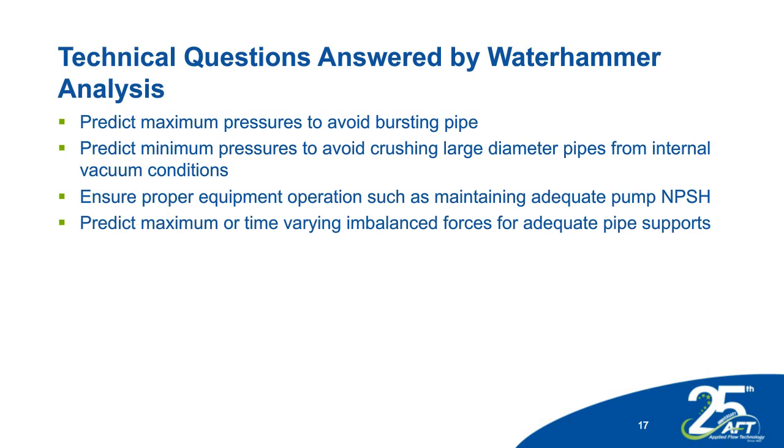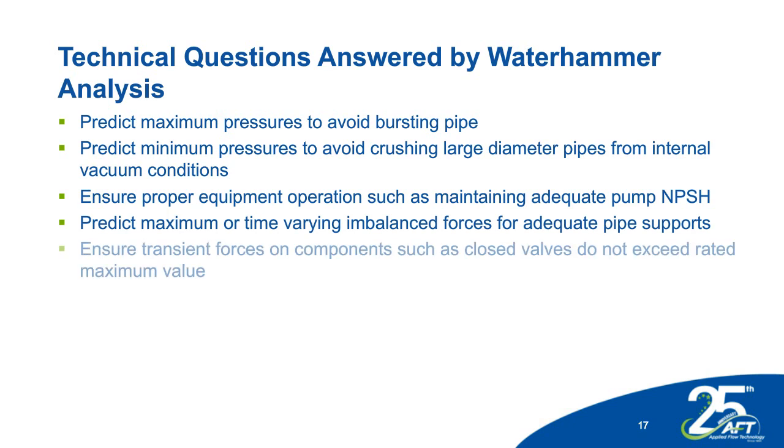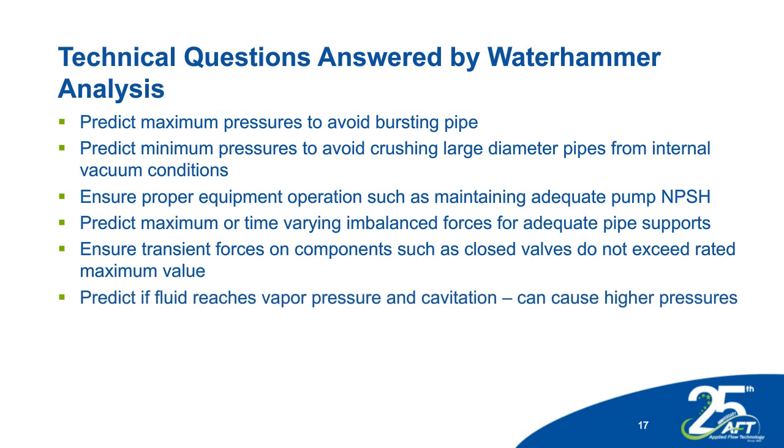It can help you predict transient forces. So when your pressures are changing throughout your system, your forces are going to be causing loads on the supports as well as your equipment. And you want to make sure that your supports are strengthened appropriately and that the transient forces are not tearing up the valves and other pieces of equipment as well.